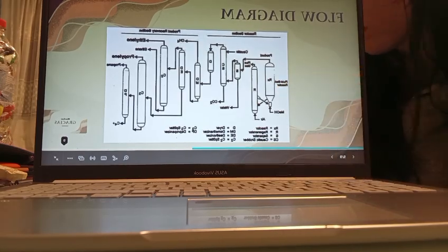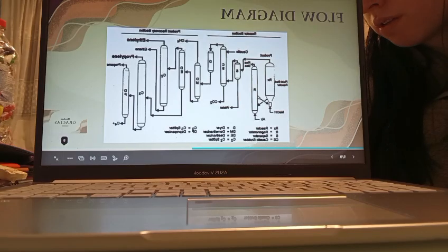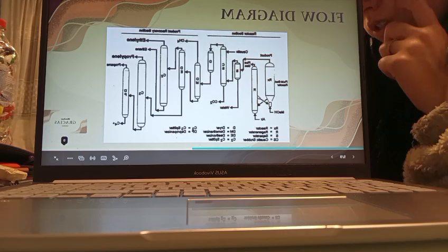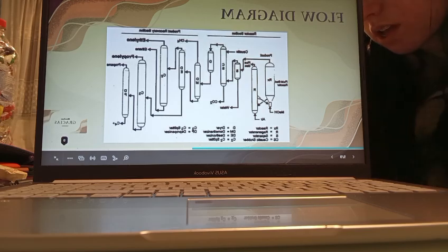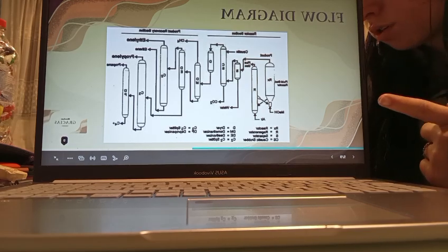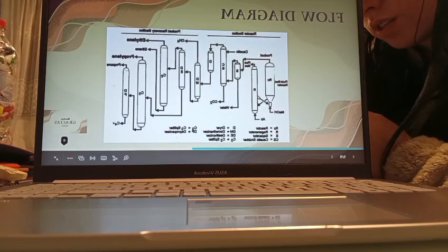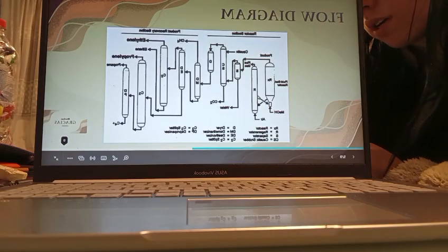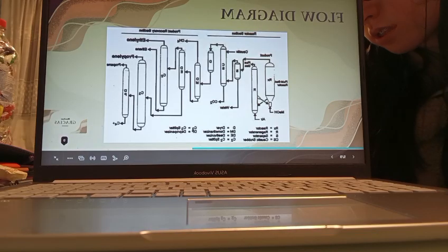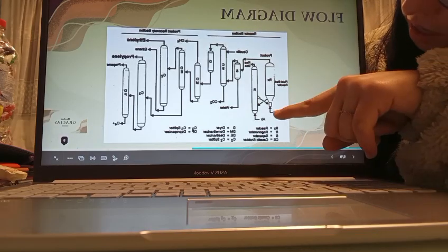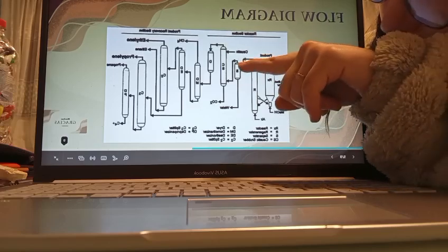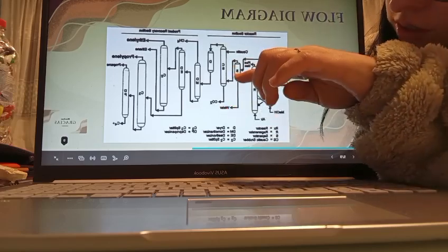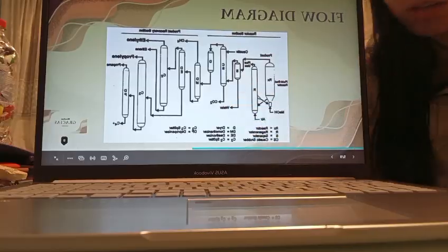This can be a fluid bed reactor, where the methanol is converted into olefins. After the reactor, the effluent passes through quench and heat recovery, which cools the stream and removes water and impurities. It passes through here, and the water and impurities go there.